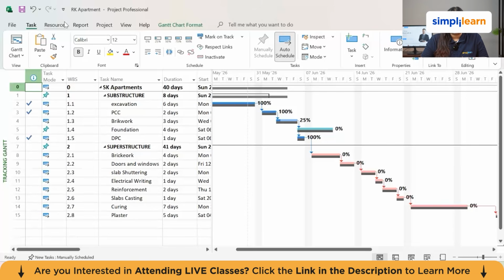By default, MS Project calculates earned value using duration percentage complete. This means if 60% of the task's planned duration has elapsed, MS Project assumes 60% of the work has been finished and credits 60% of the task budget as earned value. On a simple linear activity like painting a wall, that assumption is broadly correct. But on the construction side, many activities do not progress at a constant rate. A concrete slab pour might be 60% through its planned duration, but only 40% poured because there was a pour stoppage of 3 days due to rain or a supply issue.